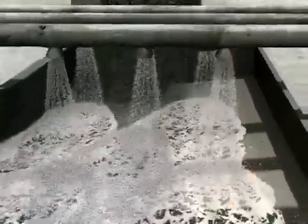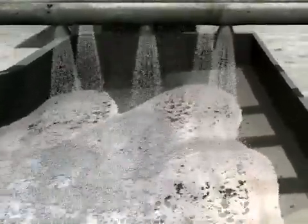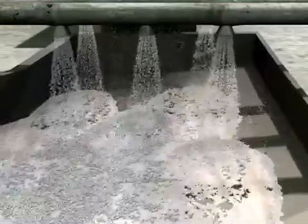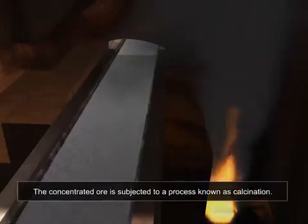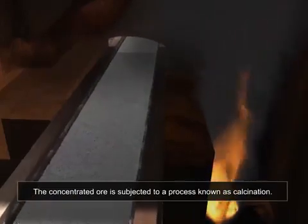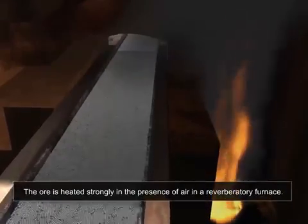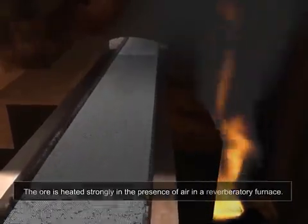The powdered ore is then washed in a current of water to remove impurities. The heavier ore particles settle down while the lighter impurities are washed away with the water. The concentrated ore is then subjected to a process known as calcination. The ore is heated strongly in the presence of air in a reverberatory furnace.